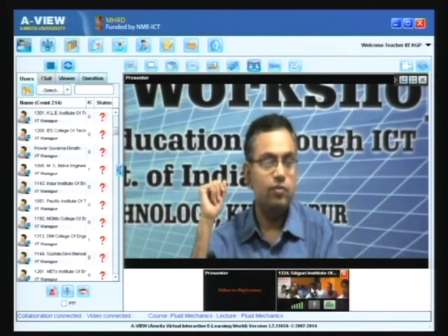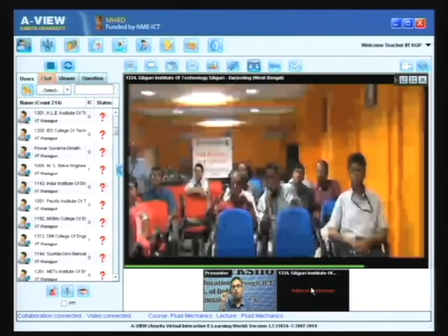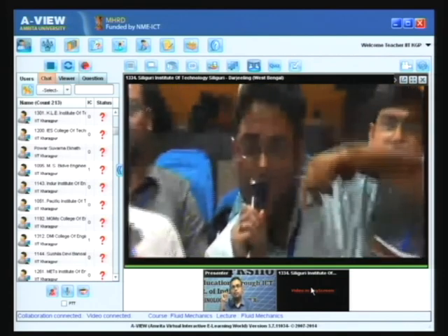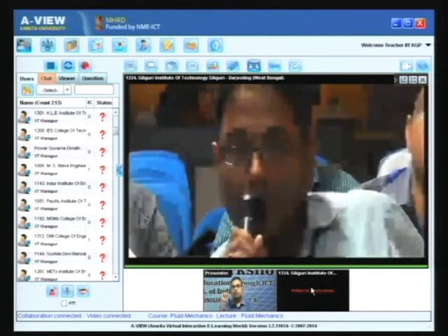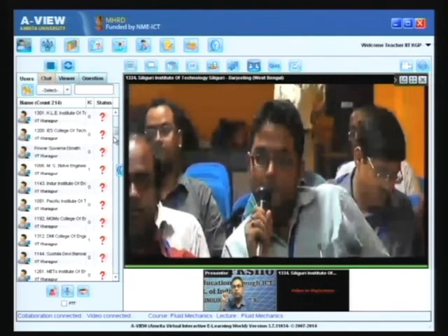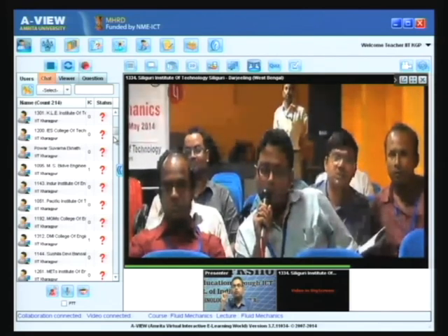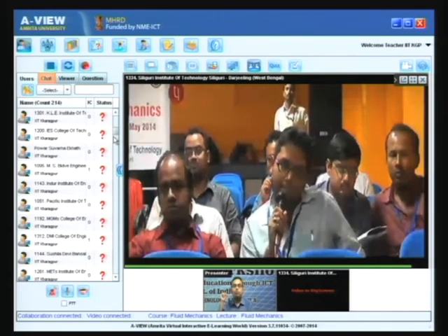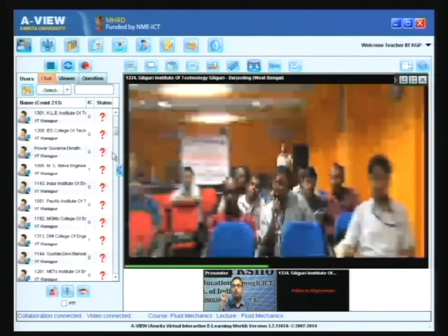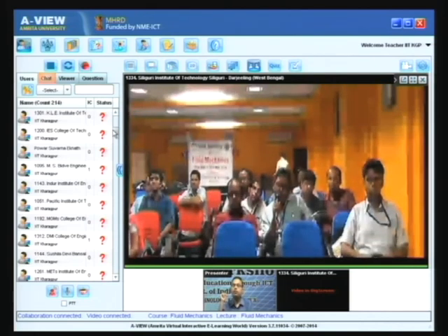Good afternoon, sir. My first question: when you discuss viscosity, the velocity gradient is parabolic. Why? It could be a straight line. No, who has considered parabolic? I have not considered parabolic. Some book that you might have read might have used a parabolic velocity profile to establish the concept of viscosity, but I am afraid that is not the right way of introducing the concept.